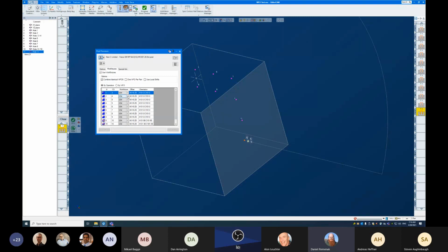And you might ask, why is that? Why are we using G54 for all of these operations? And what do all these funny icons mean over here in the left column? Let's talk about that. The work fixtures have all gone back to G54 because we don't have enough. That's why I have holes 7 and 8 that are just sitting out here, and there's nothing special about them. The reason was to make it so that there would be too many work fixtures for this post.